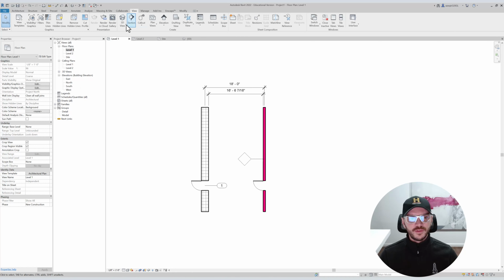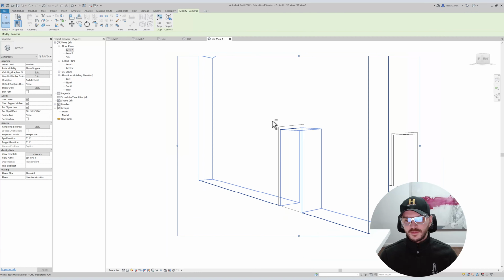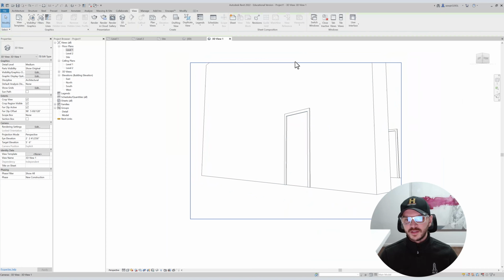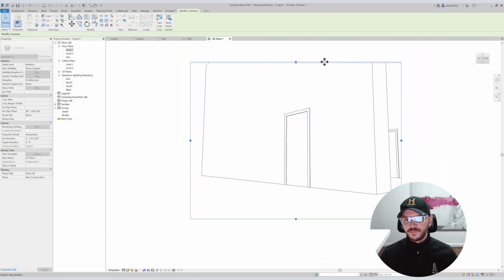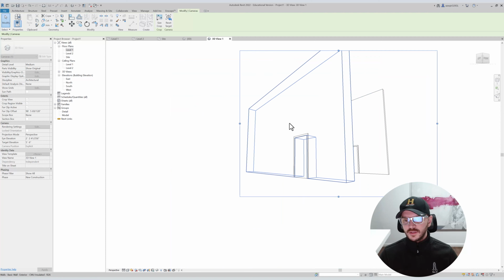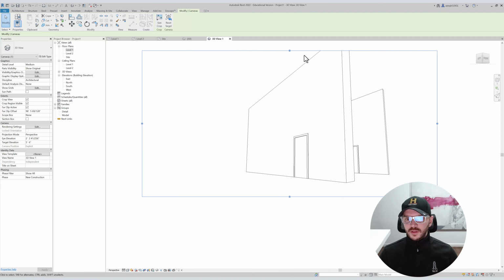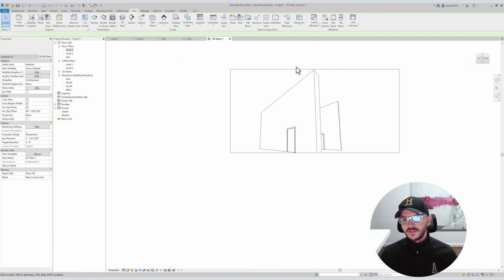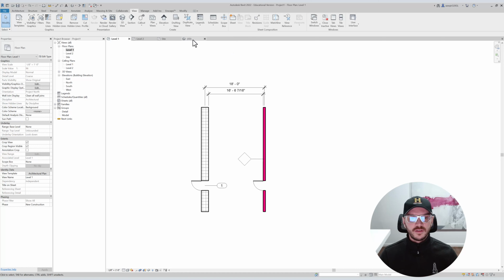If you want to pop there, it's best to do when you're in plan view, you can also set up cameras. Once you set up a camera, it'll give you like a perspective shot of wherever you put the camera, right? And then you can play around with the window here. Perspective views in Revit are just absolute trash. So I'll just tell you that and be very straightforward.